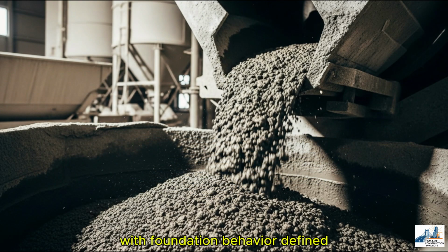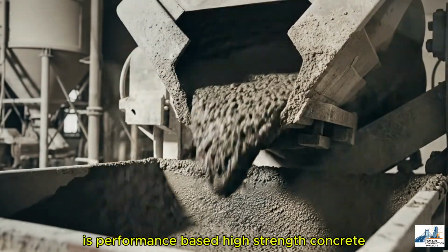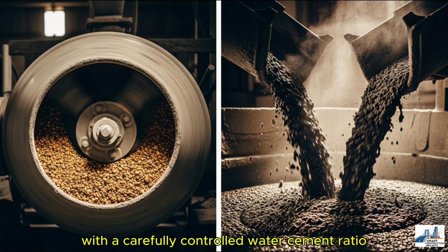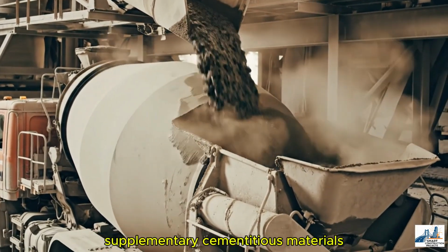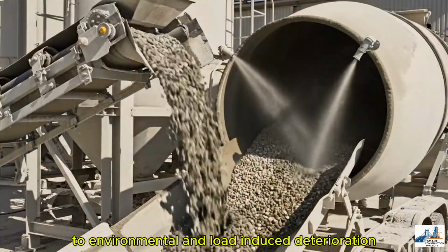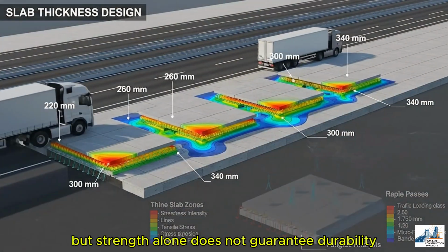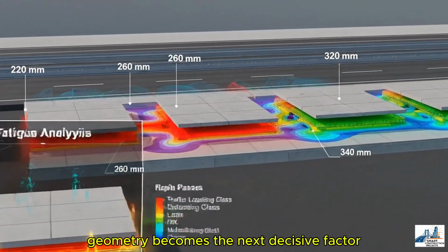With foundation behavior defined, attention shifts upward to the concrete itself. Concrete mix design for heavy traffic roads is performance-based. High-strength concrete, typically M40 to M50 grade, with a carefully controlled water-cement ratio ensures adequate flexural strength and durability. Supplementary cementitious materials further enhance long-term resistance to environmental and load-induced deterioration. But strength alone does not guarantee durability. Geometry becomes the next decisive factor.